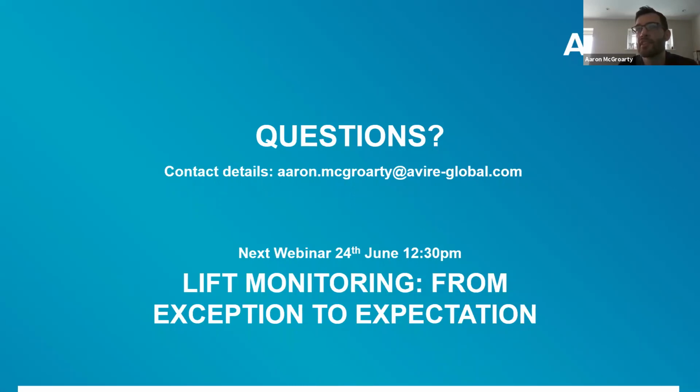Do you want to ask the next question? I'll quickly look to see what it says. Yeah, absolutely. I just quickly check myself. The lift standards for vandal resistant lift components is EN81-70, if anyone wants to go and have a look at that. There is an article about vandal resistance on our website, if that's helpful. So going back to that last question about the LRV, it is 30%. People recommend it to be 60%, but the minimum it states is 30%.